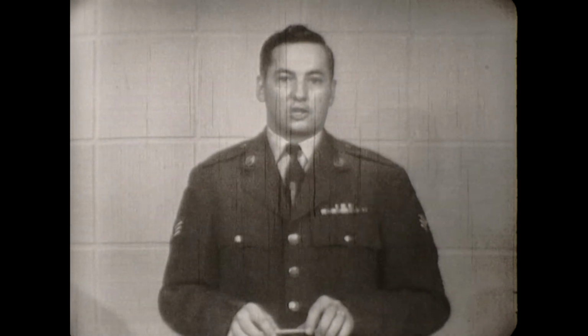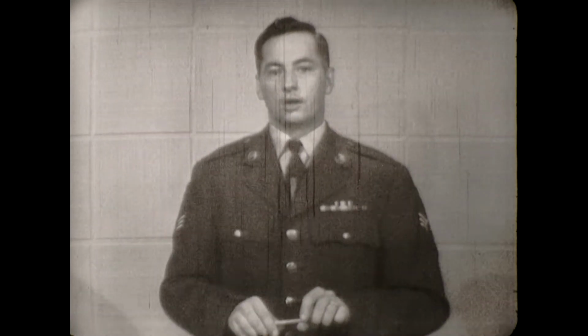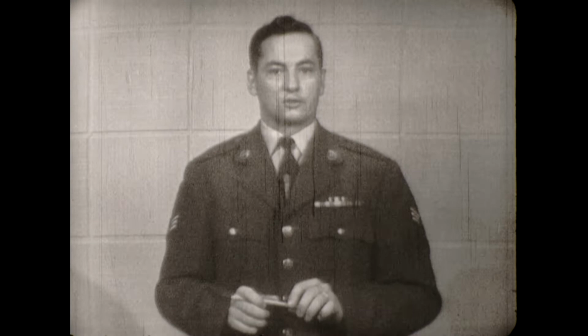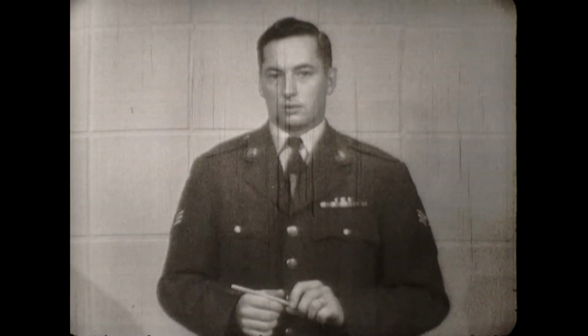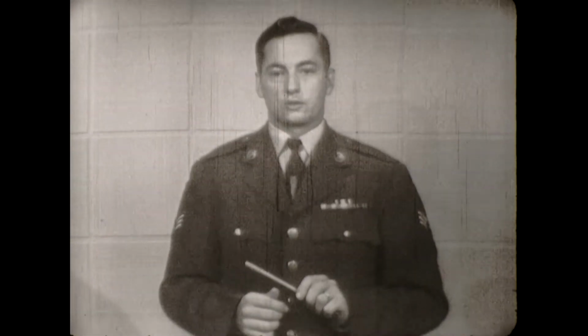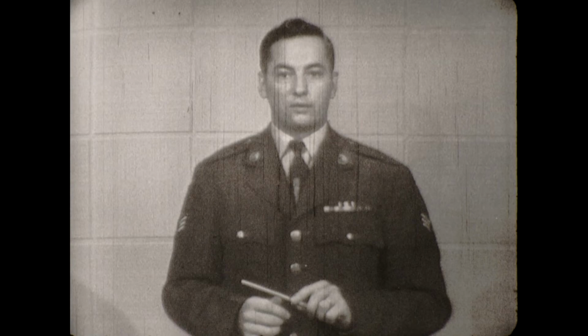Most commercial radio stations use the grounded quarter-wave antenna for broadcasting. A grounded quarter wave uses the ground to produce its image, so it has all the properties of the half-wave dipole. Now, we said that because of geographical conditions, a perfect radiation pattern was almost impossible to achieve. In a few minutes, we'll be back to tell you how the Earth and the sky and reflecting objects alter the radiation pattern.